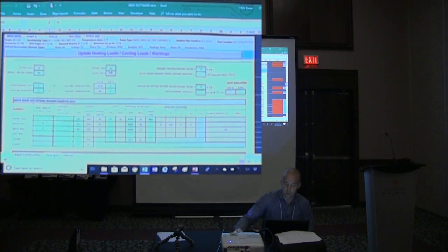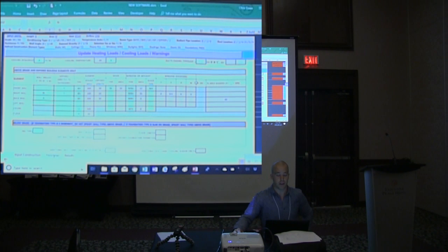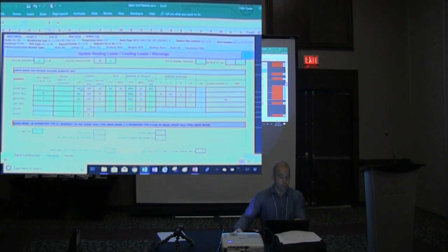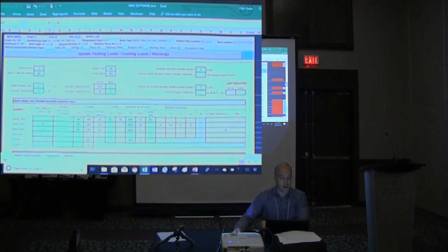Your room type, living room, bathroom, whatever, your floor area of the room, temperatures, radiant heating, ducting, all the different things you can specify. Lots of it's going to get left blank. And then here, for every room you have up to 4 walls, and is it exposed? What wall type is it? Remember we talked about wall 1, we've specified the area, the length, the door type, the window type, the overhang. So that's kind of what a room looks like.